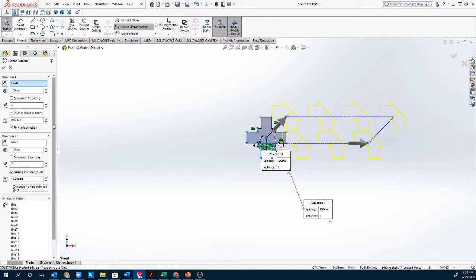So this is actually a really useful tool in terms of being able to make things quicker. The idea here is, if you're trying to do something that's a pattern that has repetition, so for example, you want to make a chessboard, you can use linear patterns to define the different blocks. Linear patterns and circular patterns are really truly your friends for getting things set up.